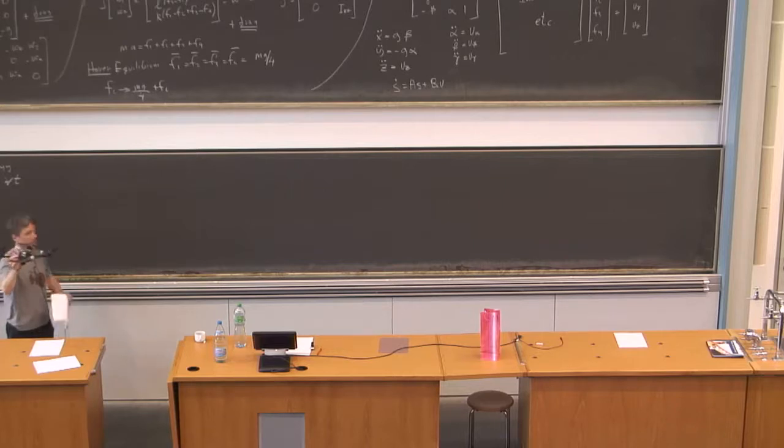And in order to do that, it's clear that I need to produce half the thrust with one propeller and the other half with the other propeller. I'm kind of jumping the steps, you can deduce this through the equations, but I'm jumping to the conclusion to tell you that if you want an equilibrium, you need F1 equal to F3 equal to mg over 2. F3, yeah, okay.